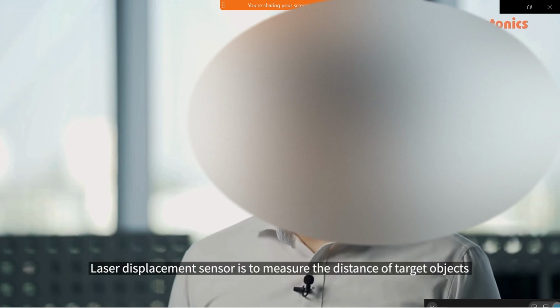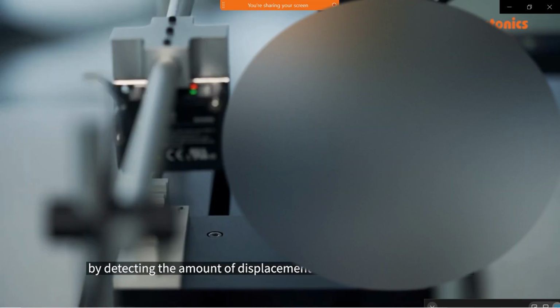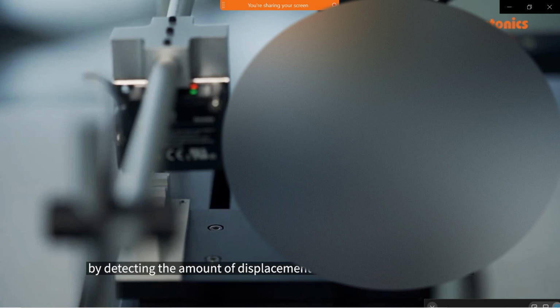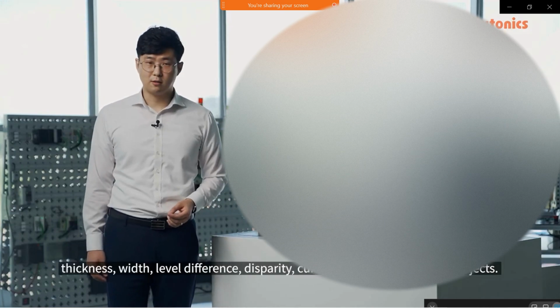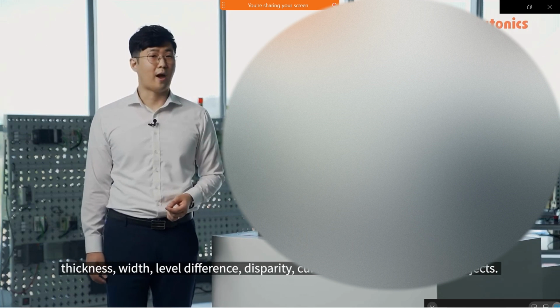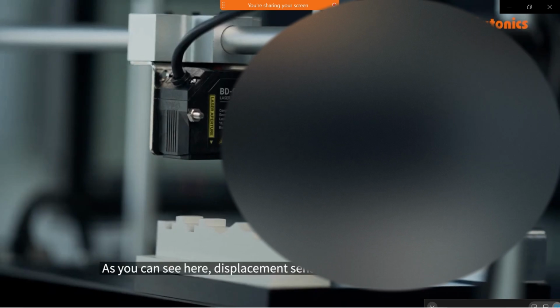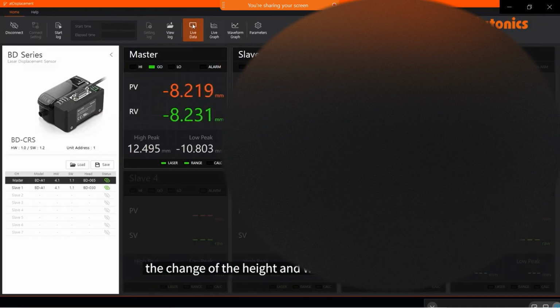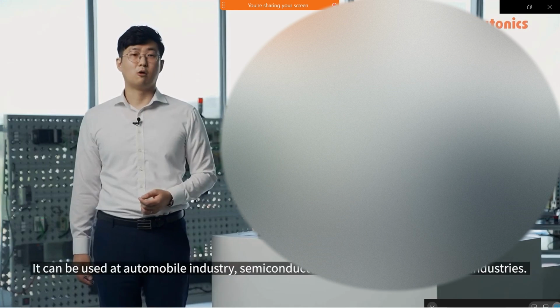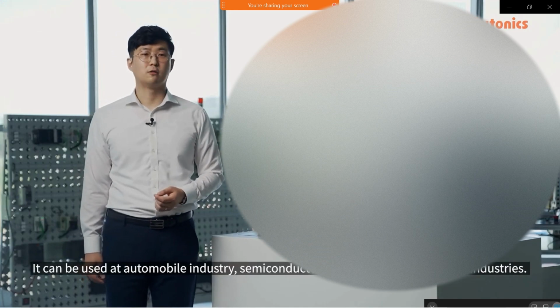Laser displacement sensor is to measure the distance of target object by detecting the amount of displacement when its position is changed. By using displacement sensor, you can measure thickness, width, level difference, disparity, curve, and evenness of target object. As you can see here, displacement sensor can accurately measure the change of the height and width of the objects. It can be used in automobile industry, semiconductor industry, and other various industries.